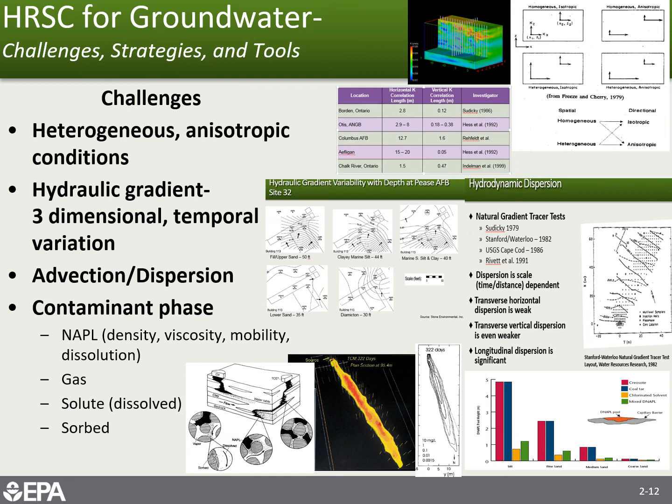When really most of the aquifers that we're living in are this one down here, anisotropic and highly heterogeneous, meaning it's going to vary. Properties like hydraulic conductivity are going to vary when you move in the vertical versus the horizontal, and also as you move around different places within the matrix itself. And that is very different from some of our early on conceptual models of how plumes behaved. In the early days, for example, many of the researchers thought that dispersion was a major factor, and that many of our plumes came out and were shaped in these large fan-shaped plumes driven by dispersion.